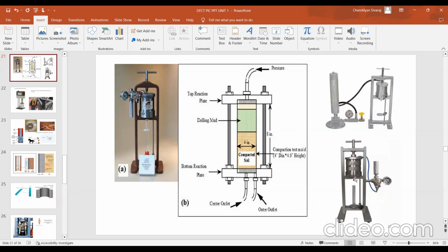The liquid which passes through is called the filtrate, and the cake which sits on top is called the filter cake. The filter cake sits on the filter paper, and the filtrate passes through the orifice as well as the filter paper and is collected in the graduated cylinder. The experiment is performed under high pressure, high temperature conditions, simulating an industrial setup or a well exposed to HPHT. This is a very simple experiment.